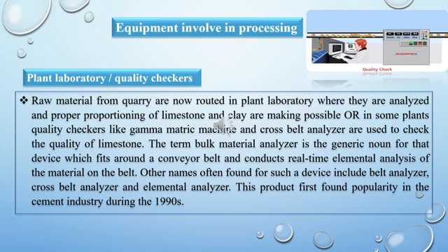As well as we have discussed non-hydraulic cement, the cement which does not become hardened in the presence of water but becomes hardened when it is reacted with carbon dioxide, which is known as carbonation. After that, we have said that when chemical inputs were changed, then we can get different types of ordinary Portland cement. So we did this and we got different types of cement, in which we have discussed colored cement, hydrophobic cement and many more.